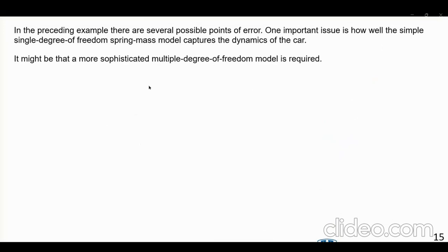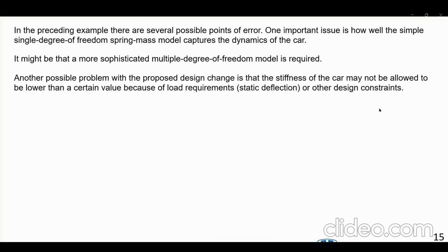Now, the problem is that there are some issues that are overly simplistic. We made the problem overly simplistic here. For example, we assume a single degree of freedom system. The car is not a single degree of freedom system, or if you use a more refined model, such as multi-degree of freedom system, you have more confidence. The second one is that we reduce the stiffness, okay?